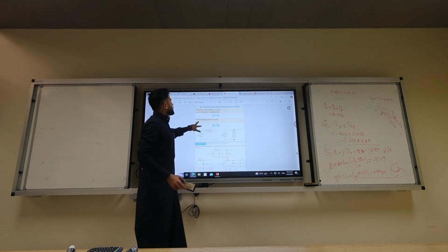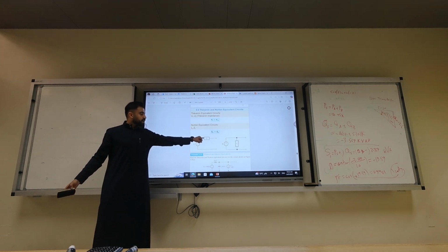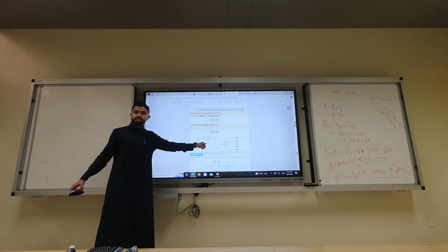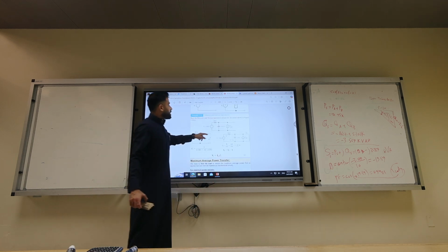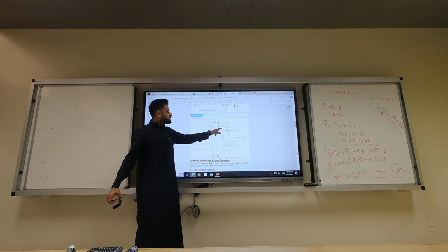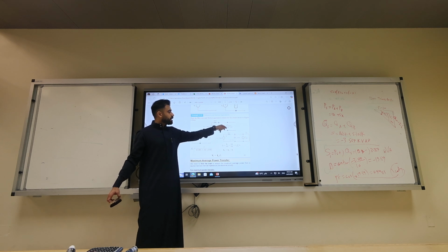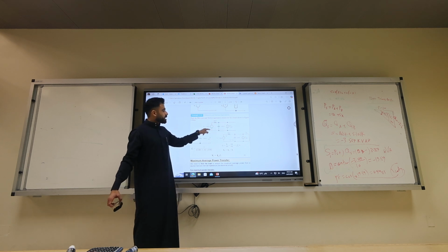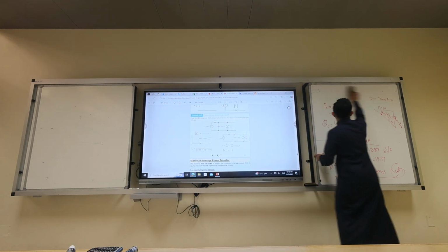Thévenin and Norton equivalent circuit. Do you remember Thévenin and Norton? So we can replace a resistor with a box called impedance Z and Norton with impedance Z. What is the equivalent impedance? It's what? 100 parallel with minus 300, because we kill the current source, we short circuit the voltage source. So what is 100 parallel with minus 300? Do it with the calculator.